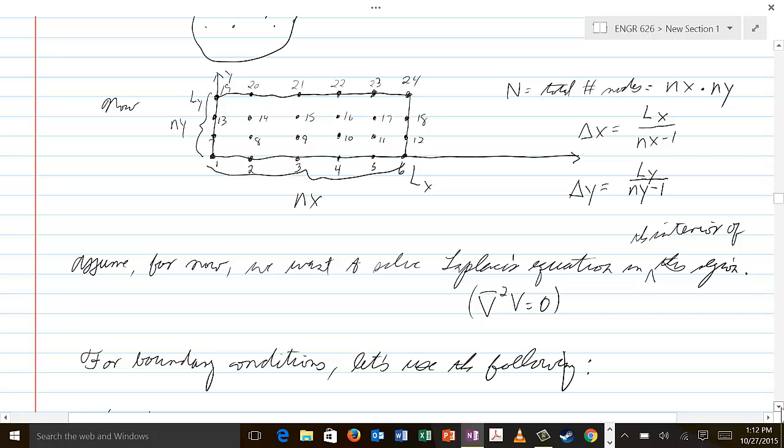So you can see how the number grows rapidly, and in fact in 3 dimensions it would not be uncommon at all to go to 20 by 20 by 20, which gets you up to 8,000 nodes. So increasing the dimension of your problem domain generally dramatically increases the number of nodes in the problem, which means that the matrix size is larger, and also means that the solution time required for the problem is larger.